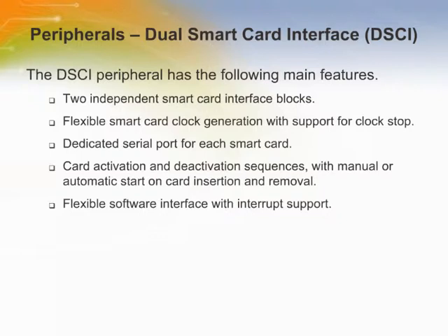The dual Smart Card Interface module provides 2 complete Smart Card Interface peripherals, independent of the single DSCI function available within the dual USART peripheral. The 2 DSCI cores in the dual DSCI are identical and are independent except for the shared clock and interrupt signals. The data input and output signals can be linked by the port configurator into a single bidirectional open drain signal or left as two separate signals, as appropriate for the hardware interface to any particular smart card.